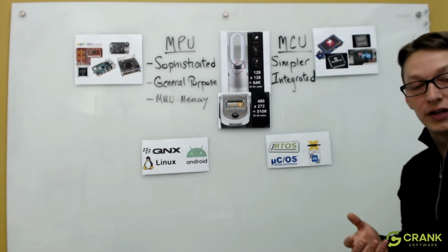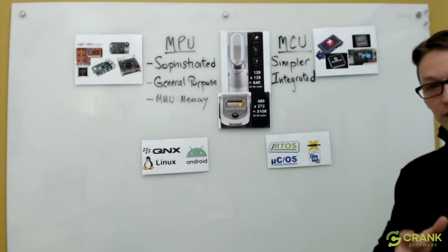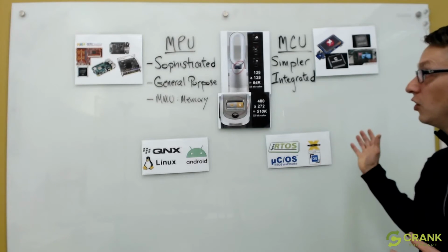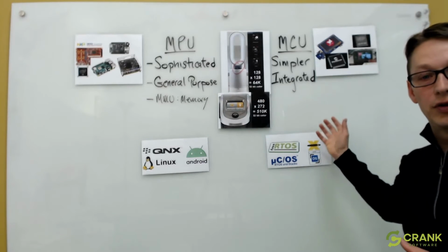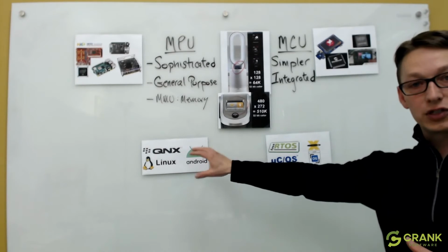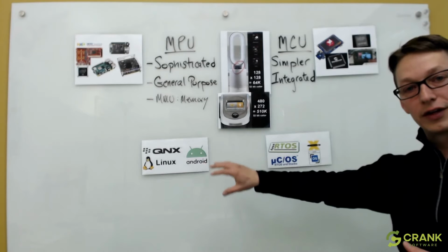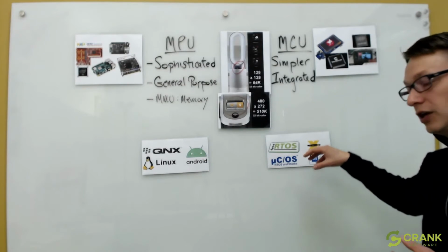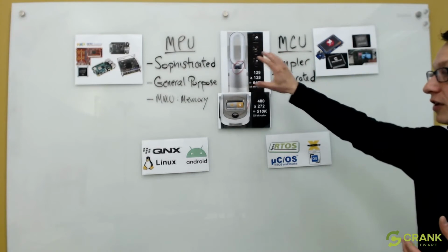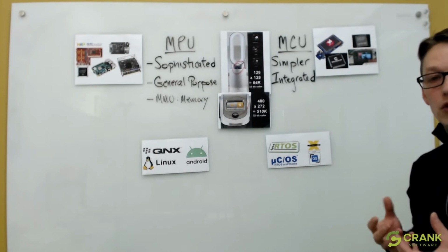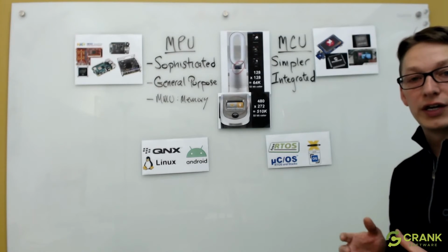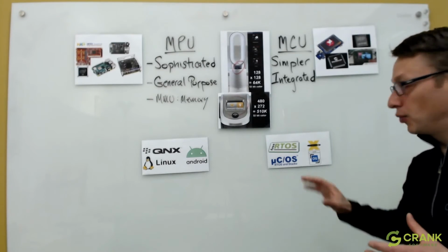But ultimately, when you actually want to see the display running and interact with it, it's important to be able to not just have a simulation environment, but to run on the real hardware. And this is where Storyboard excels, because regardless of whether you're using an MPU or an MCU, our technology allows you to use a common development model to bridge back and forth between different deployment models, whether you're deploying to QNX, Linux, or Android, or to a FreeRTOS, MicroC/OS, or ThreadX type of system, agnostic of the hardware, agnostic of the rendering technology. You can pick the platform that gives you your development support so that you can quickly iterate change on the embedded UI and then put it into context rapidly.